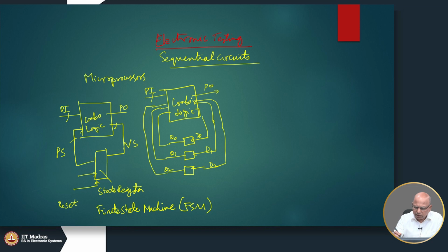There are gates in the combinational logic and they have delays. So, there is no guarantee that these 3 signals will be ready at the same time. It is possible that one of them takes a little longer than the others.